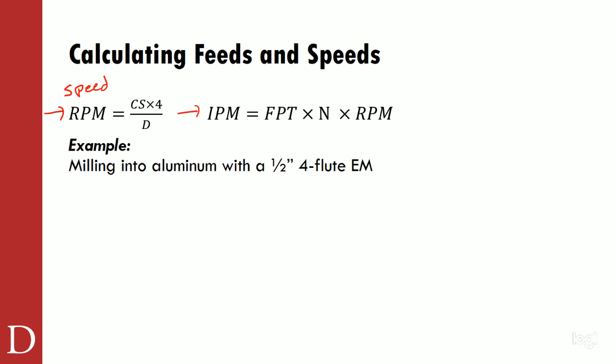But the other one is the inches per minute. How hard do you want to press this thing down into the material? It goes without saying, there's lots of things that determine that, right? Things like, what's the diameter of the cutter, right? So if I'm using a little 1/8 inch drill in my cordless drill and I try to feed it too fast, I'm probably going to break that drill.